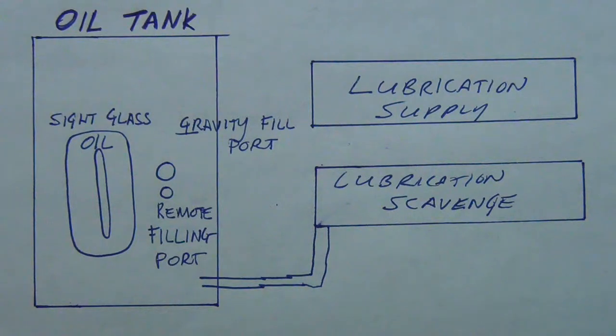Covered quite a bit. That gives you an idea on the supply circuit with the scavenge circuit. You have oil from the oil tank. You've got that flow of oil going through filters to the lubrication units, basically to distribute through nozzles the oil to the engine bearings, the accessory gearbox, then to the transfer gearbox.